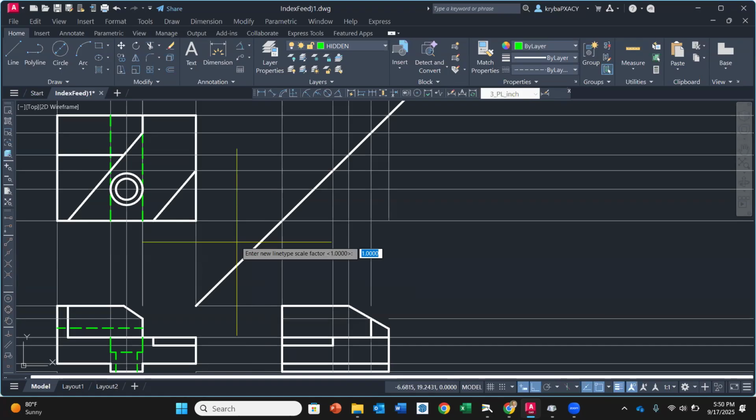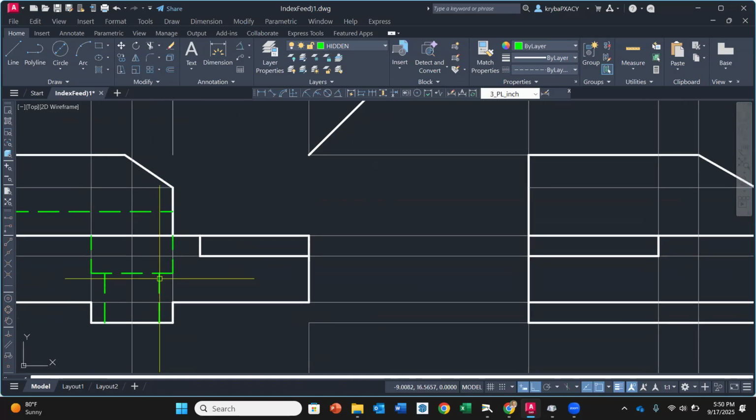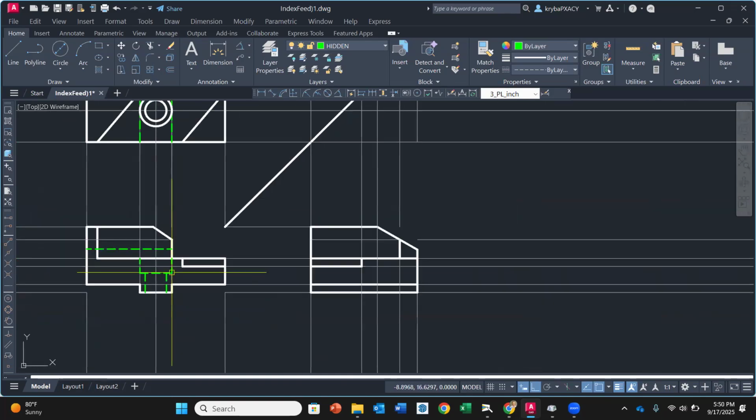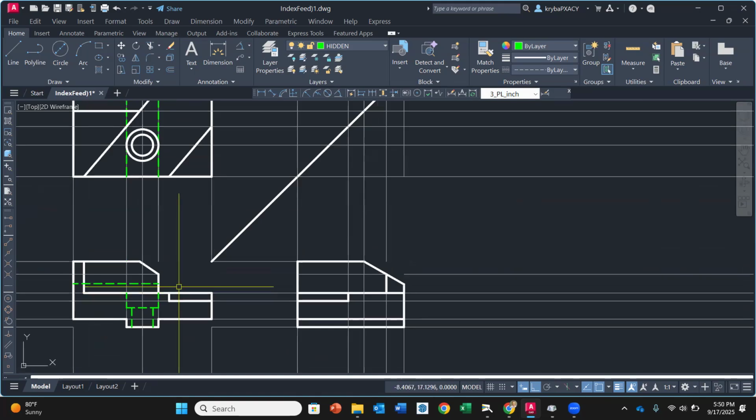I don't think it has to move half because I think it's going to be kind of small then. So we're going to move it to 0.75, enter. And notice that I now have a nice break there without it being too small. So 0.75 is a good number. I will be looking for that on this stuff. Those are details you have to pay attention to, okay?